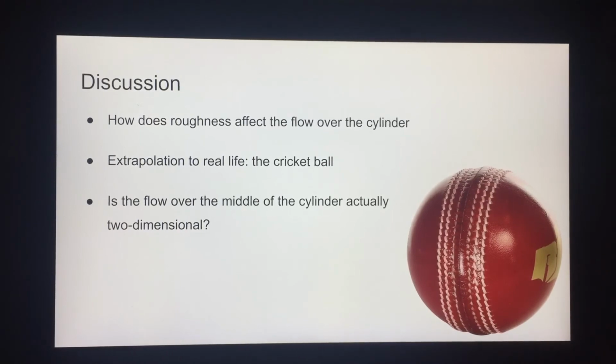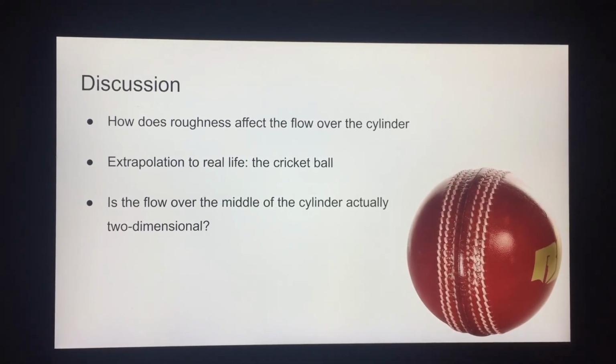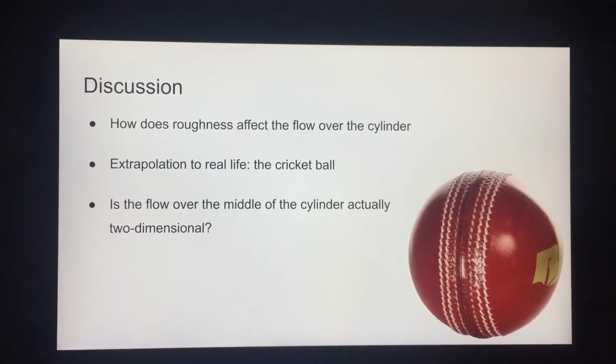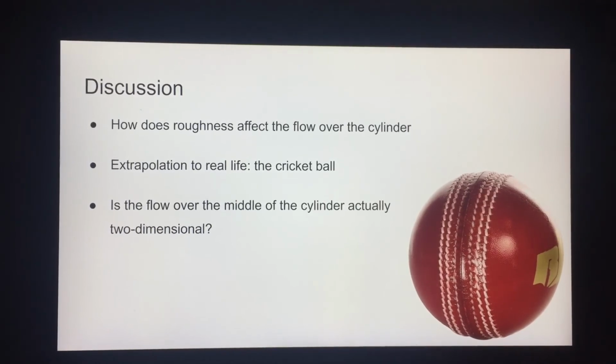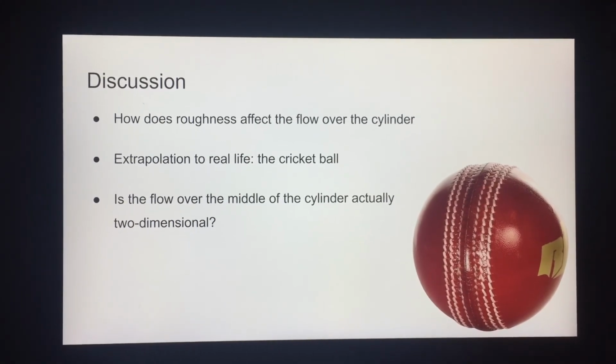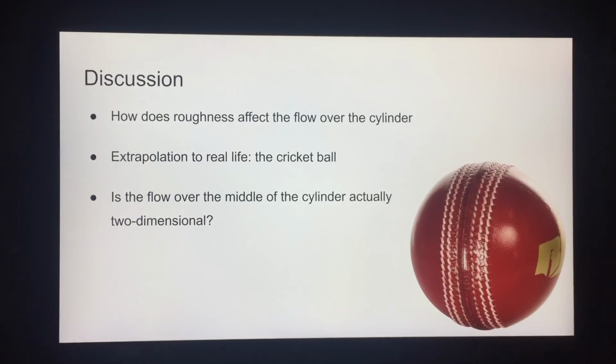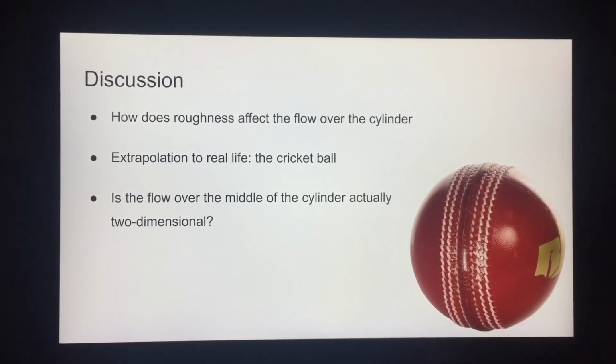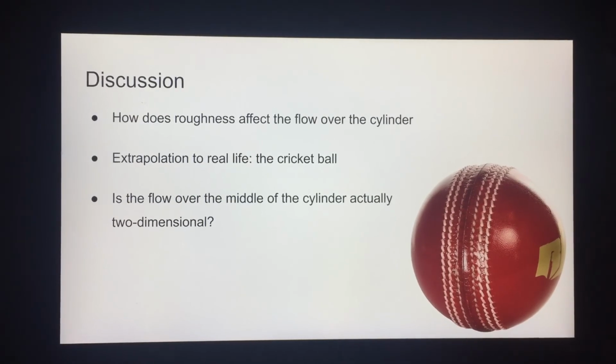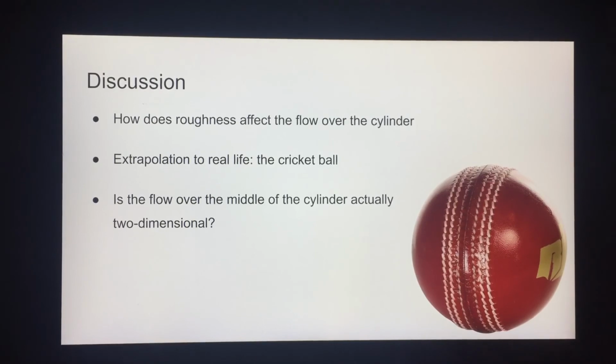And addressing the question, is the flow over the middle of this cylinder actually two-dimensional, as the experiment is designed to produce? This probably isn't the case, because it is likely that the boundary of the wall affects the flow.